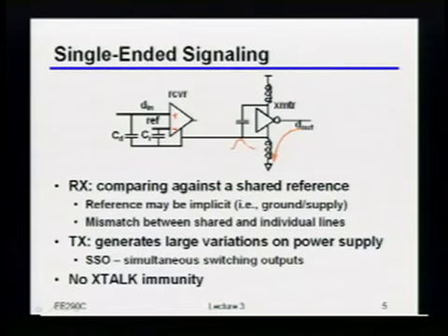Okay? The other issue, which again we spent a lot of time talking about and which is highlighted here in a cartoon, is that given that I have these ground return paths with large inductance in them, anytime I pull some current through that, I'm going to cause this bounce over here, which is going to cause the entire chip to move around relative to chips on the other side, or really relative to the board ground.